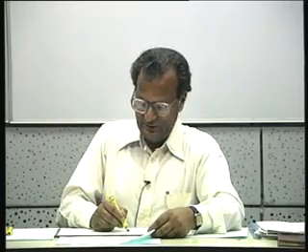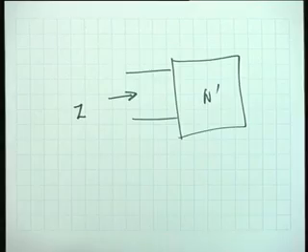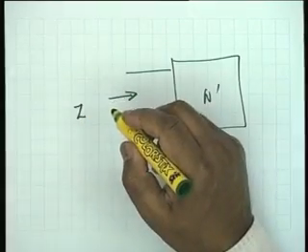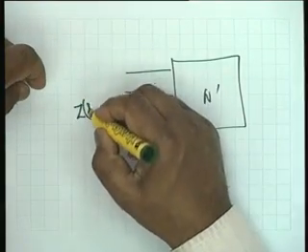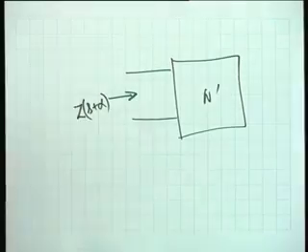The impedance of an inductor is L times S plus alpha, and the admittance of a capacitor is C times S plus alpha. What are we trying to do? What is our objective? Our objective will be clear in a moment. We are trying to derive another network N prime whose impedance, instead of S, shall have S plus alpha. This is what we wanted to derive.